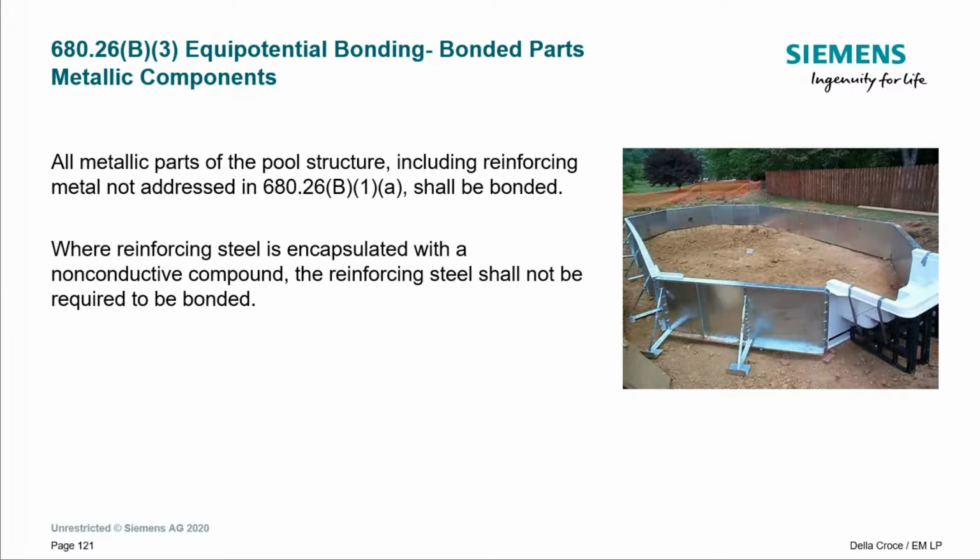So you could say, well, okay, let's give that up. It doesn't fit in there. But it's certainly metal within 5 foot of the pool. It certainly is. So no matter what you say, this has to be bonded. I think the next question associated with these types of pools is, do I have to bond every section, every little piece? I get that question, and I've talked to folks about that. I honestly haven't taken the time to do the research. I kind of give guidance to say, well, go look at the manufacturer's installation instructions. I see if these pieces are bolted together, and I think that they act as one piece when finally completed. You would think so.